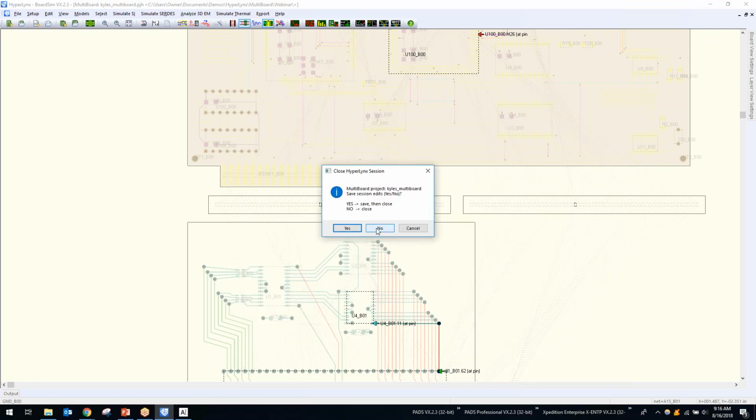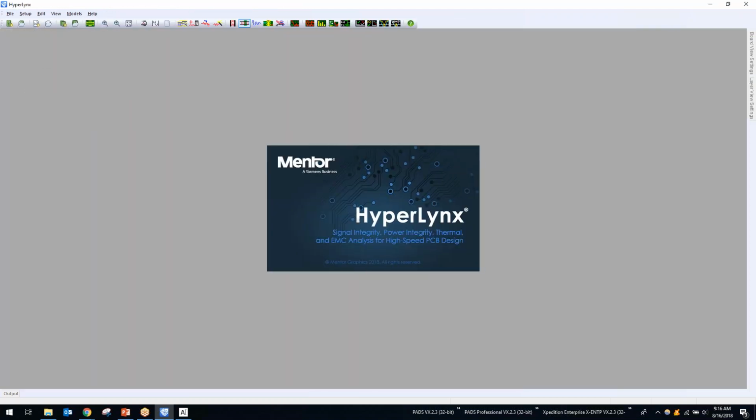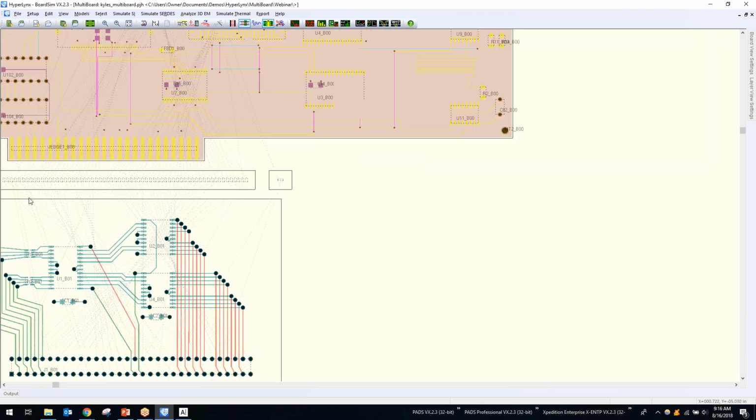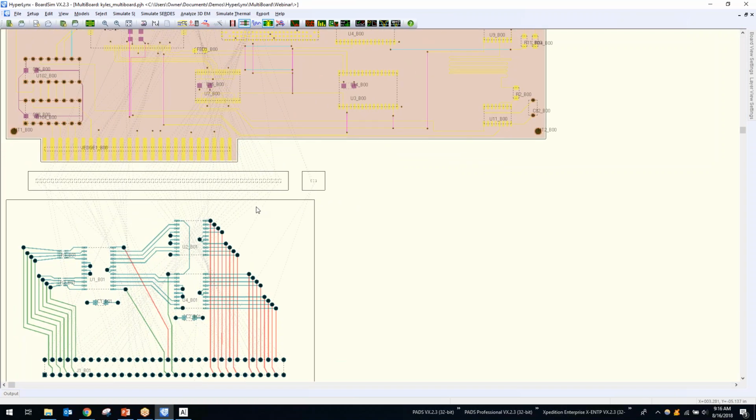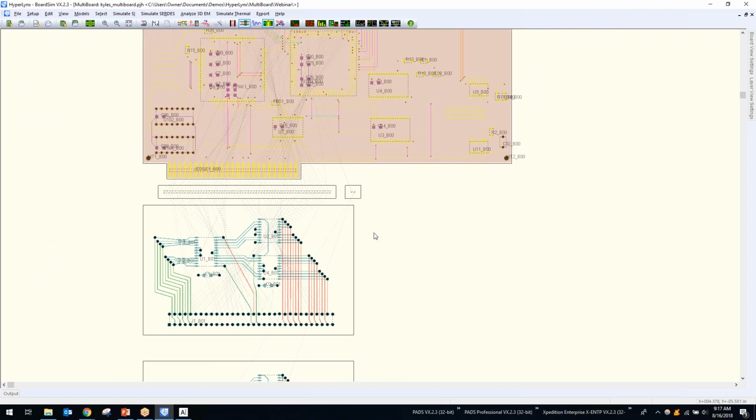Okay. When I hit finish, now we'll see that instead of those 2 large RLC connectors, we have a much smaller connector that has been defined through that S parameter. So then once you have the S parameter set up as your connector model, again, we can go ahead and just run a general batch wizard or interactive sweeps or the simulation, and it'll be now using that more accurate model for your connector.